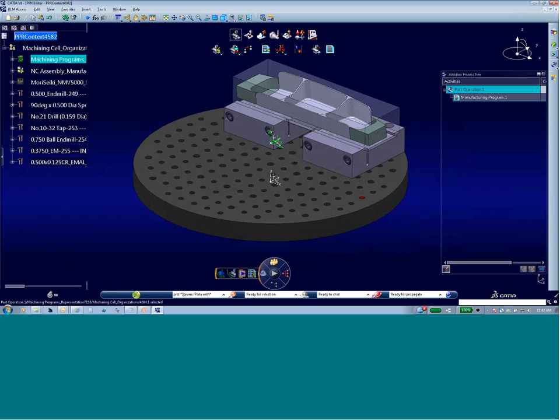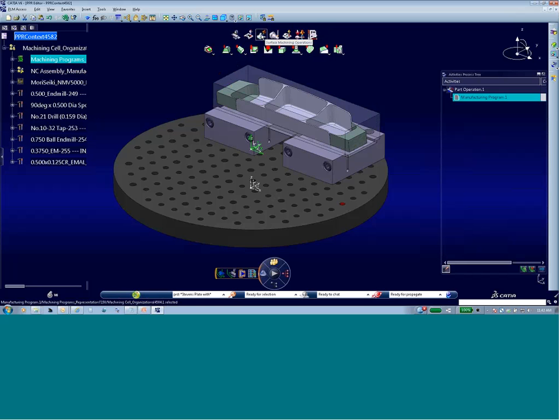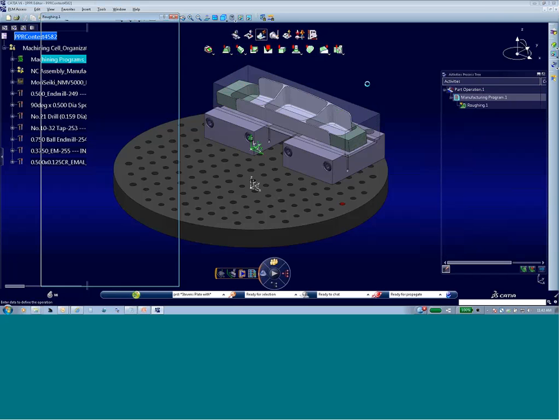Okay, so after that I want to add, again, I'll keep this short so we have sufficient time here. I'm going to add a couple of machining operations. I think I'll start out with a roughing operation. So the way these menus work, you'll notice each one of these has some number of functions. If I switch the main menu items, these are surface machining operations, which actually include all of the 3-, 4-, and 5-axis machining operations that are available. So as you see these toolbars, there's additional functions down here. Let's put in just a roughing operation initially, and I'll try to do this quickly.